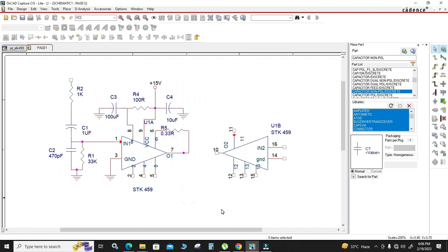Okay, so here you can see this dot, it means that it's not connected properly. The dot comes only for 3 joints, so here only 2 joints are there, but the dot should not appear. So you click this one and drag the line here. Okay, the dot does not disappear.